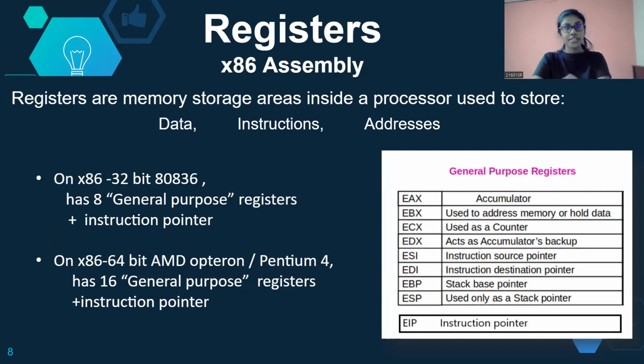Registers are temporary storage locations that are directly accessible by the processor, used to store data, instructions, or an address. Registers are very fast since they are very close to the processor. From the assembly programming language perspective, registers are like a set of variables with predefined names. Let us know more about the registers in accordance with this architecture.